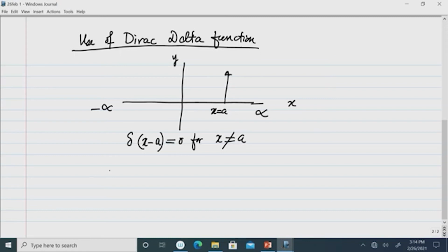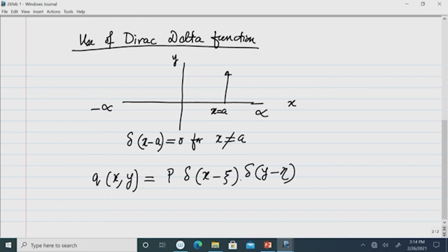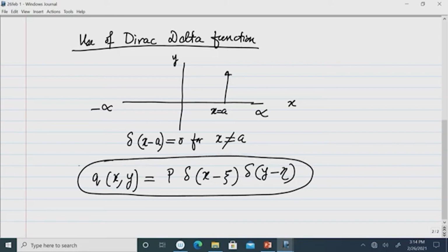So, the equivalent distributed load in the plate subjected to the concentrated load we can write as follows. Suppose the load is acting at the coordinate where the x coordinate is xi and the y coordinate is eta. So, q x is now expressed here like that. The Dirac delta function has a very important property, by use of which the calculations are simplified.